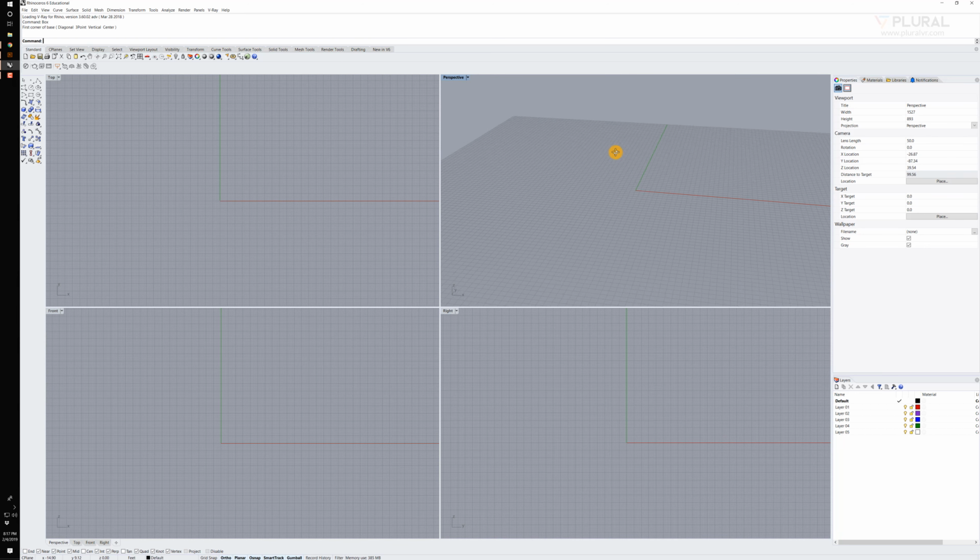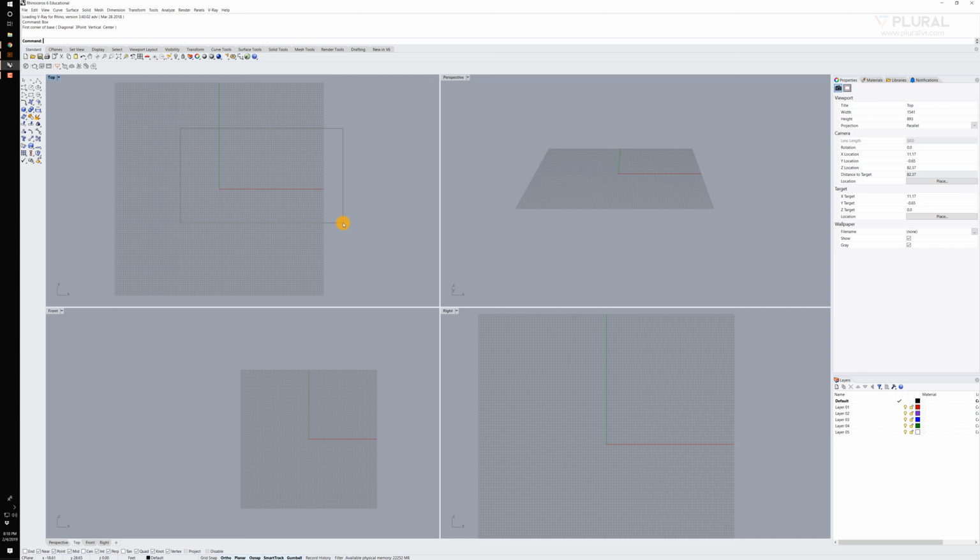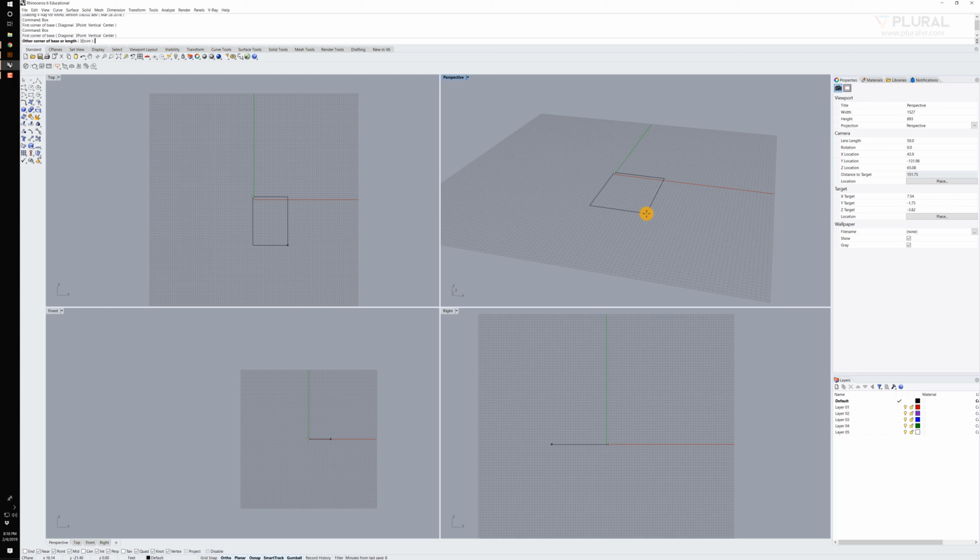Left click selects things. In class we looked at dragging from left to right does a solid box, and right to left does a dotted box. We'll look at that again in a second, but first let's make a piece of geometry. Let's go ahead and make a box. In my perspective view, I can simply click and drag. Rhino lets me enter dimensions, so if I said 10, 10, 10, this is now a 10 unit by 10 unit by 10 unit box.